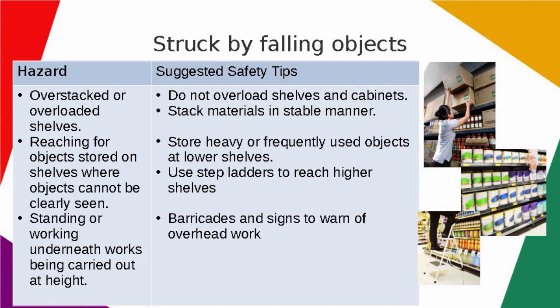Stack materials in stable manner. Store heavy or frequently used objects at lower shelves. Use step ladders to reach higher shelves. Barricades and signs to warn of overhead work.